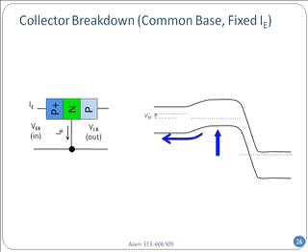Again, the current will come in and forward bias the junction. Current will flow over, and once it starts getting into the collector region, it has a tremendous amount of electric field. As a result, there will be impact ionization, right? How much energy do you need?